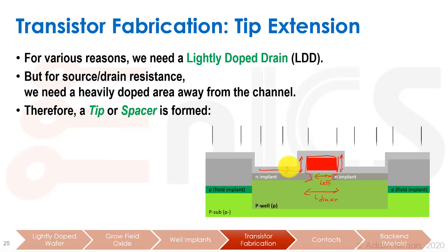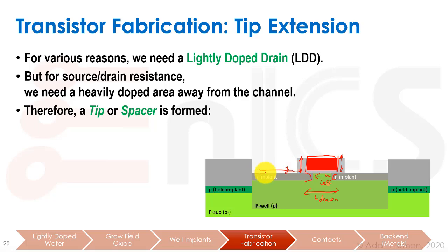Okay, and therefore if I etch it away at a constant rate, and I just want to etch it away until I touch the surface of the silicon, what happens is I etched away everything that was over here, but here I didn't etch away all that much, and therefore this excess oxide is left here on the sides.